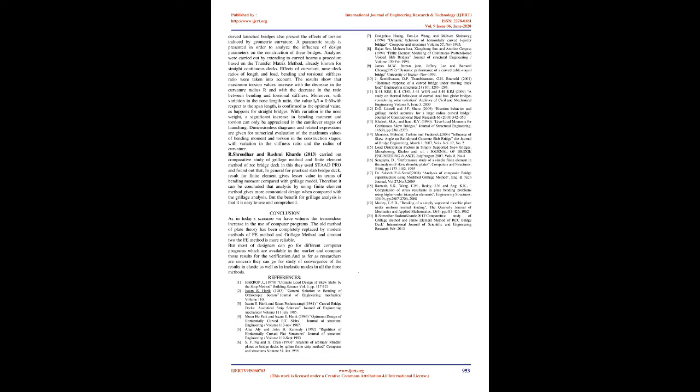For this reason, temporary stresses in the deck, during launching, are rather different from those occurring in service life. Horizontally curved launched bridges also present the effects of torsion induced by geometric curvature. A parametric study is presented in order to analyze the influence of design parameters on the construction of these bridges.